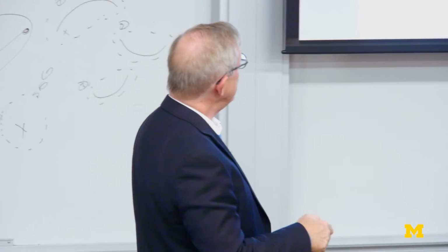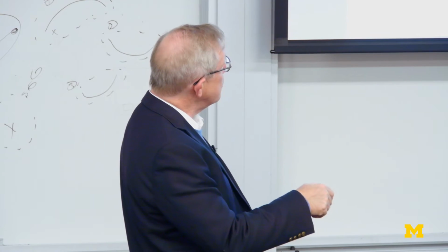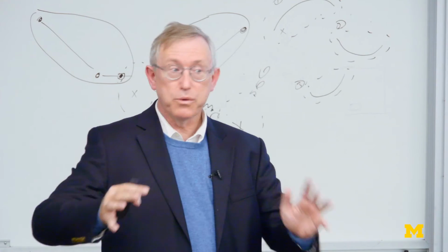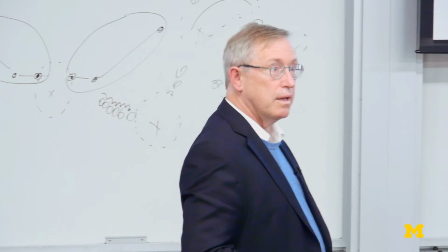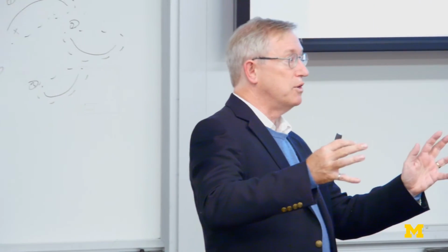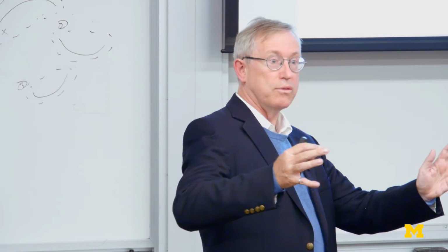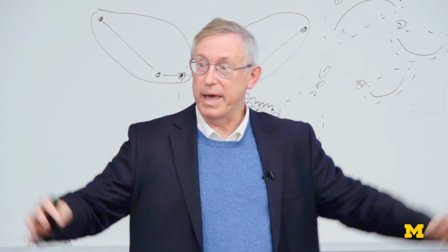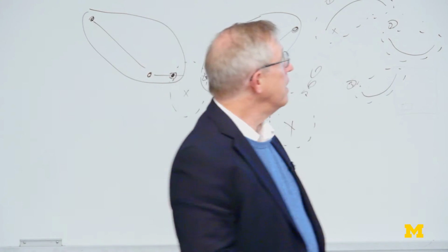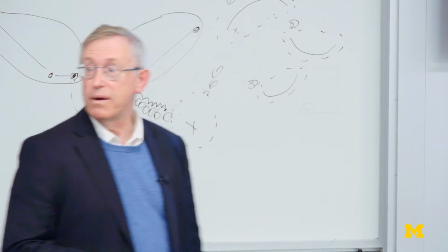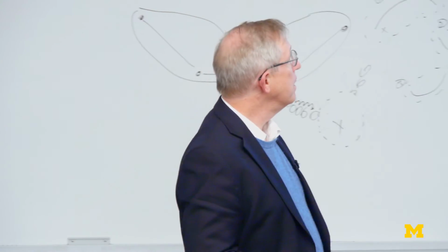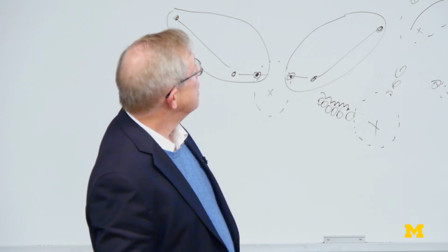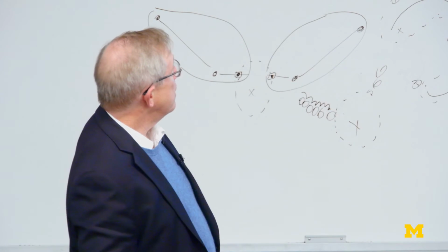And of course, because of the nonlinearity, the channel of interest will see spectral growth, right? Your own signal will interact with itself and leave its band. Furthermore, everyone else's signal is growing and interfering with you, and so you're going to get all kinds of interference effects. Okay?